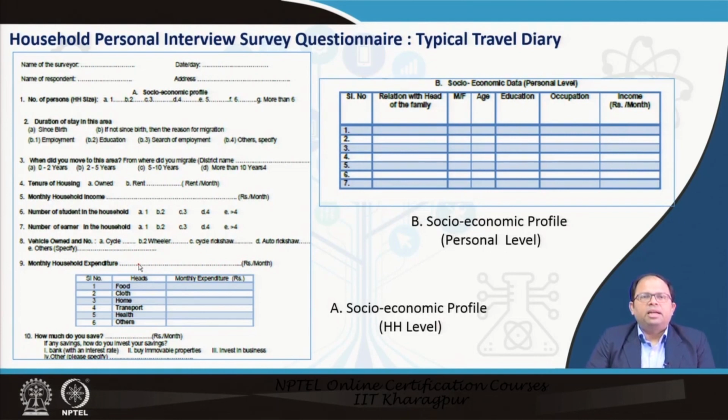So the next survey that I will explain is a typical travel diary, and this could be conducted at the household through personal interviews. As you can see in this survey, the first part of course starts with the survey details, like the name of the surveyor, the name of the respondent, the date and time, and the address where the survey is being conducted. This is to trace back in case there is some problem. We can go back to the person's house, or we can call the person back, and we also have a record of at what time the survey was conducted.